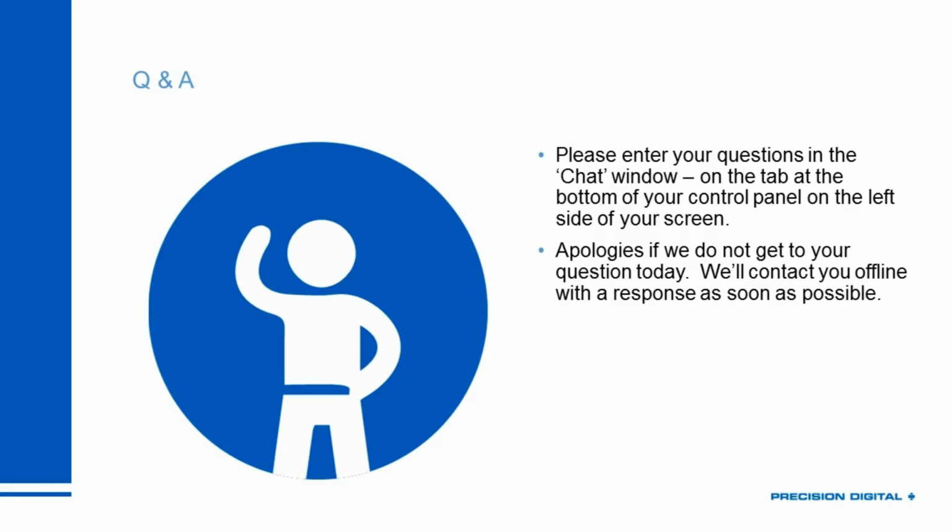Okay. Question from Derek. Do you need to factor distance in when you're considering voltage drop? The short answer is no. You'll find the answer to that question talked about more in depth in the first webinar in this series, which we mentioned earlier is available on predig.com. But the long story short is the voltage drop of wire is going to be so low that you'll almost never run into that being your problem. You could run it several thousand feet, and I can almost guarantee you you're not going to have to care what that voltage drop is.